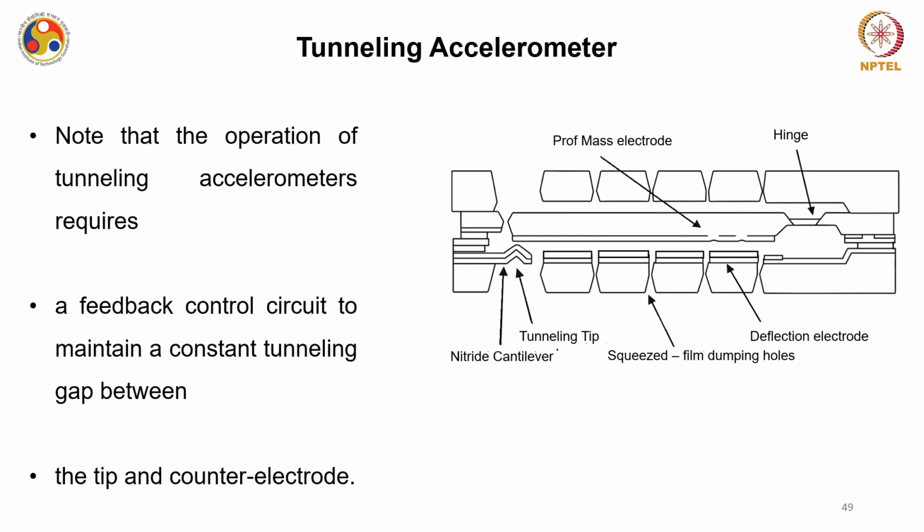Please note that the operation of the tunneling accelerometer requires a feedback control circuit to maintain a constant tunneling gap between the tip and a counter electrode.